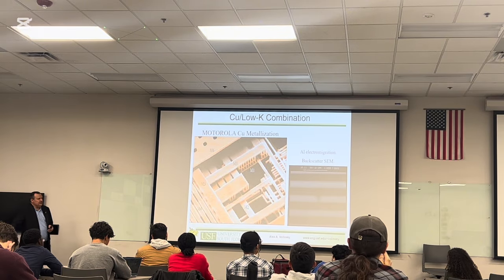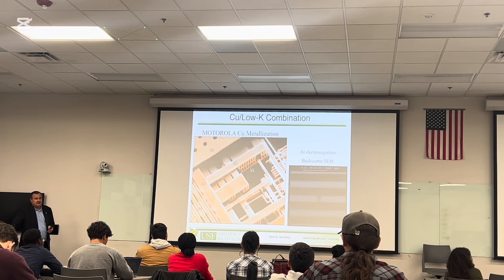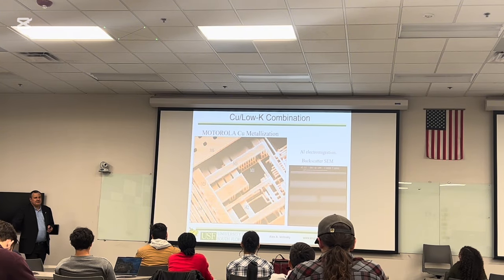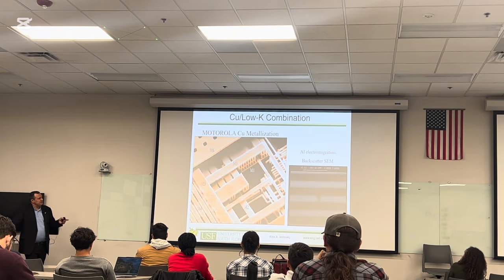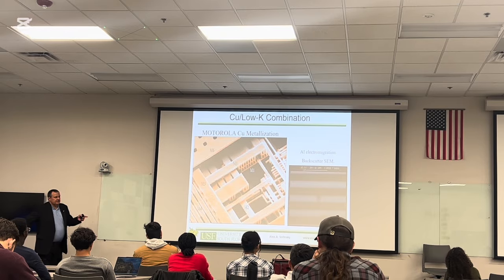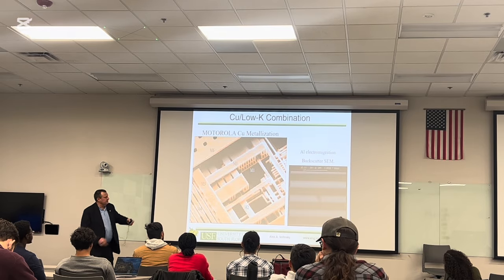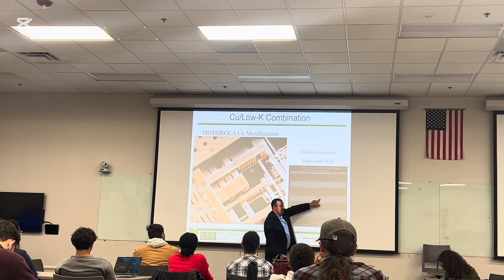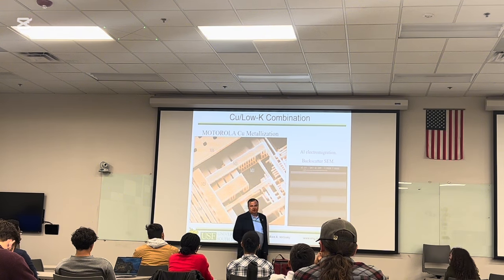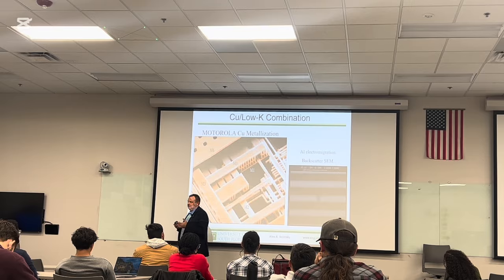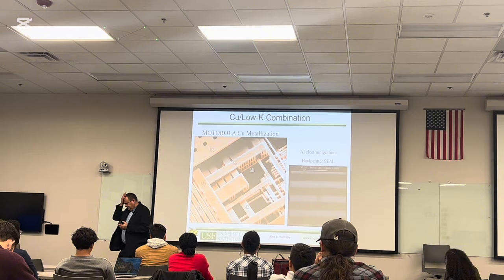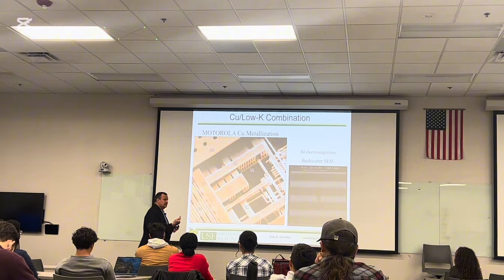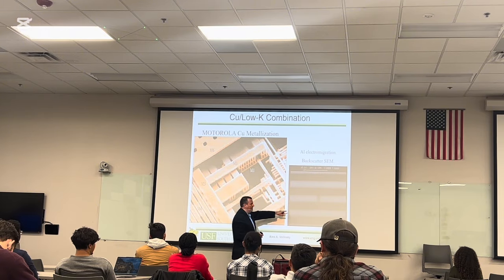I happened to work at Motorola before, and it took tens of years to develop the copper process. That's what you see over there. On the right, I've actually taken that picture. What you see over here is aluminum wiring, and there's a void because when the current density is very high, the electrons transmit momentum to atoms and physically knock them out of the way.